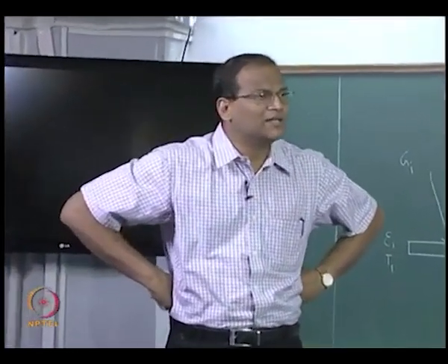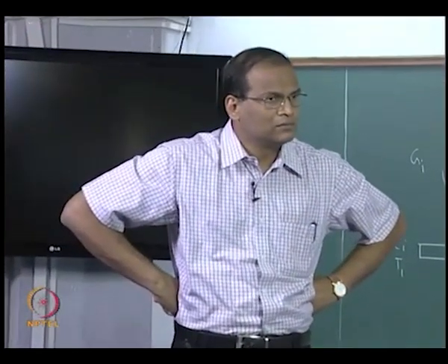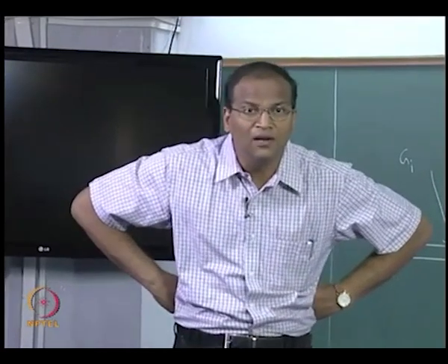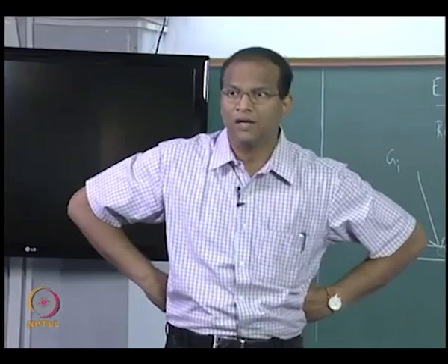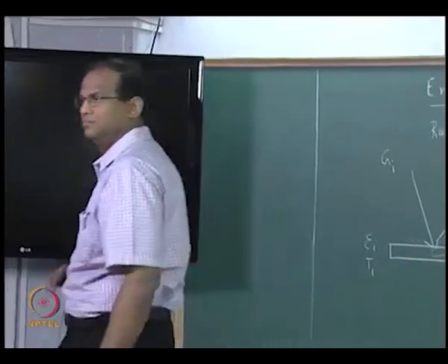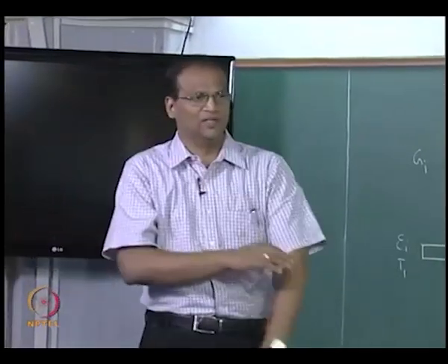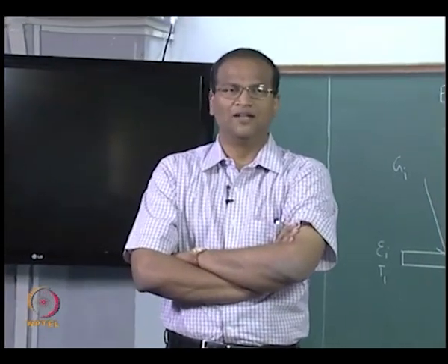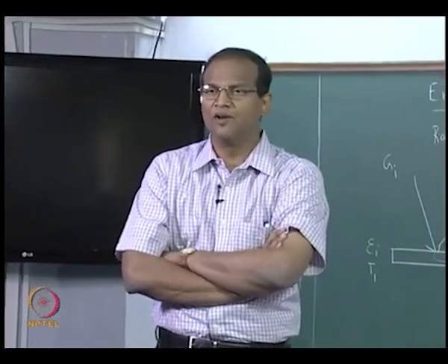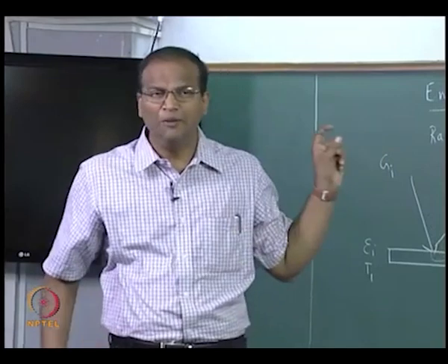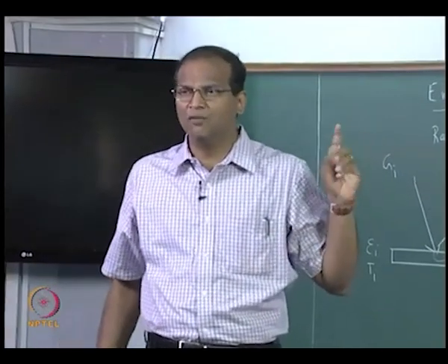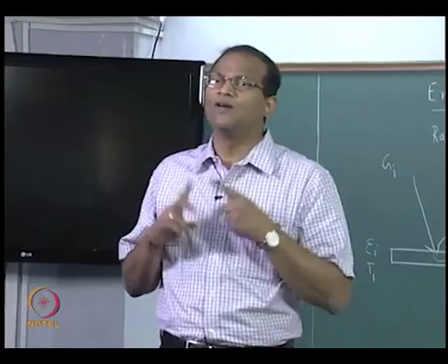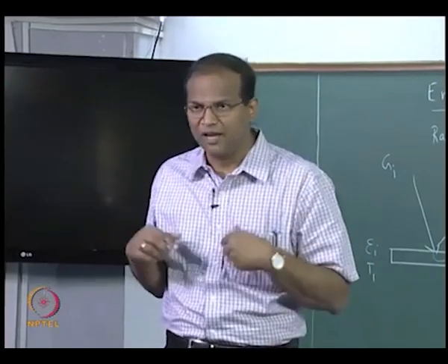It is a remarkable result, because the radiosity of a re-radiating surface is independent of emissivity. Very significant result. The radiosity of a re-radiating surface is independent of the emissivity, and it will come to an equilibrium temperature Ti depending upon whatever irradiation it receives from the neighboring fellows.